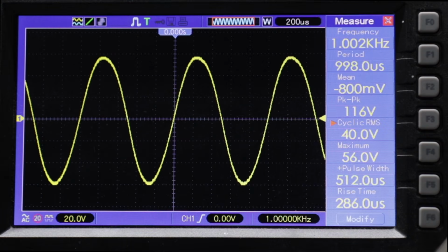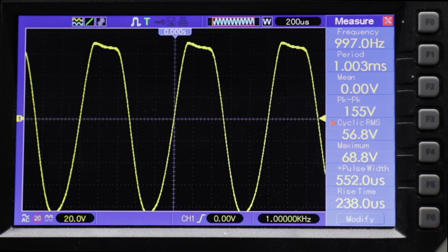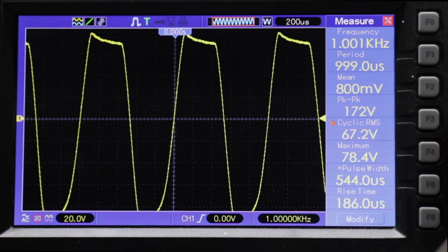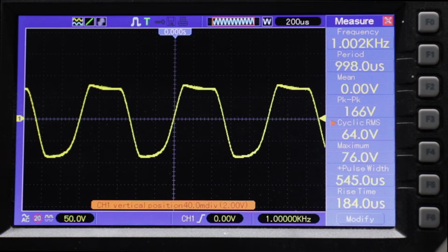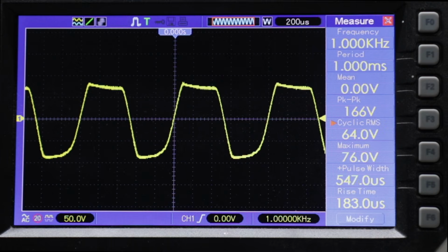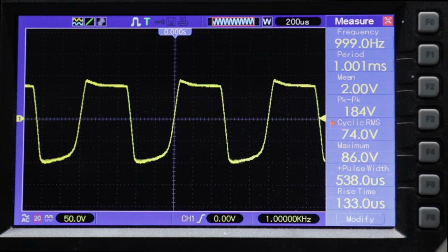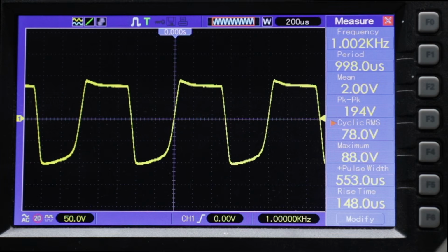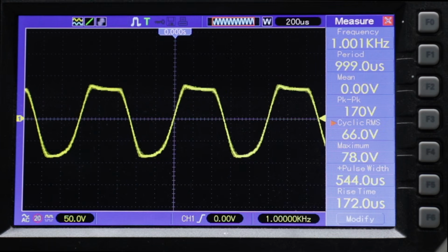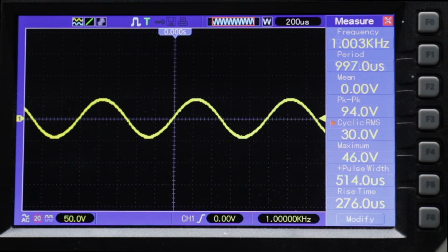So we're in the middle position because that's biased in what I would call the middle zone, the sweet spot, if you like. And if I increase the gain here, I'll just bring the scope back to 50 volts per grid. As I bring this gain up, you can see the clipping on either side of that wave. I know it's not perfectly symmetrical, but you can see it's clipping on both sides. Bring the gain back down again, bring it back up.